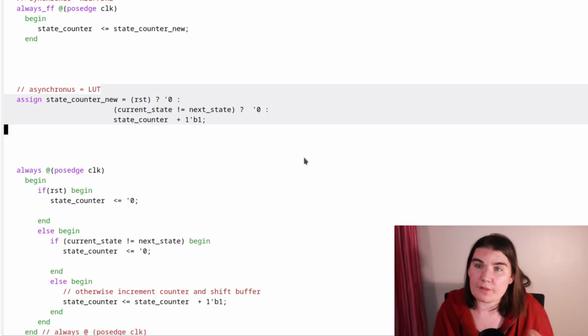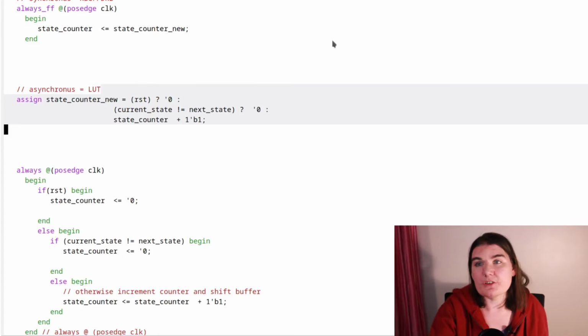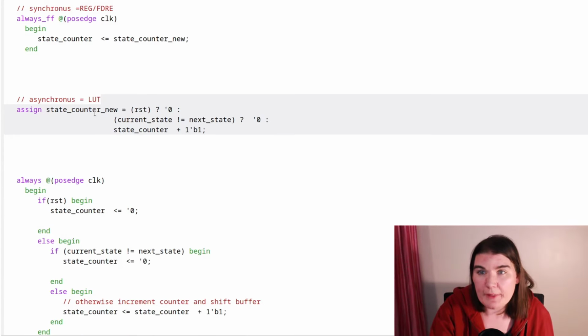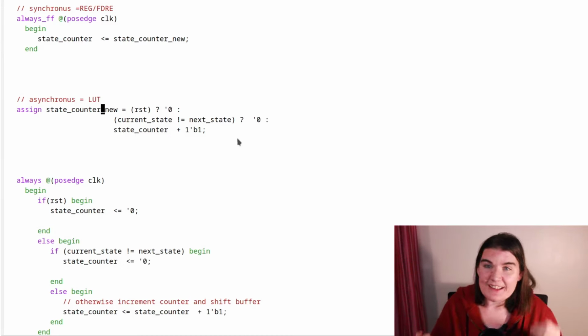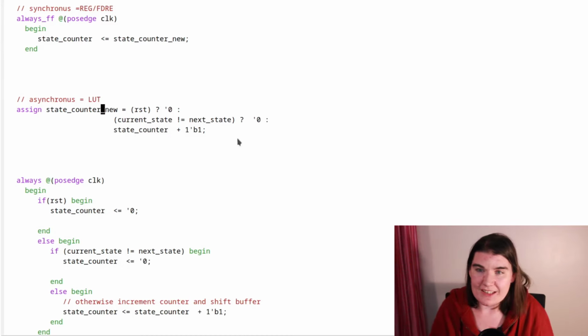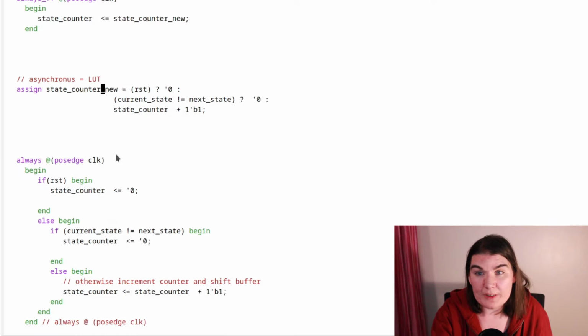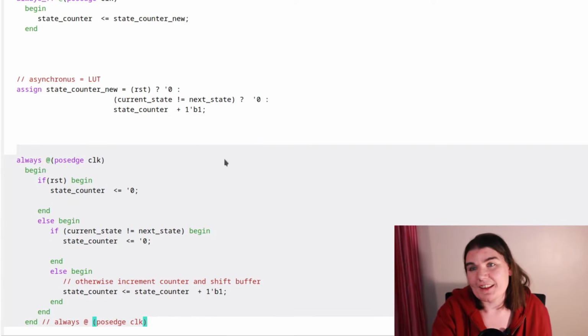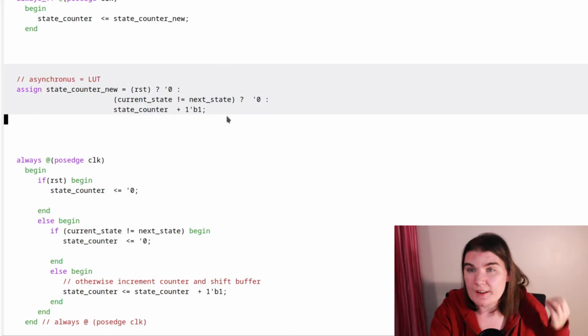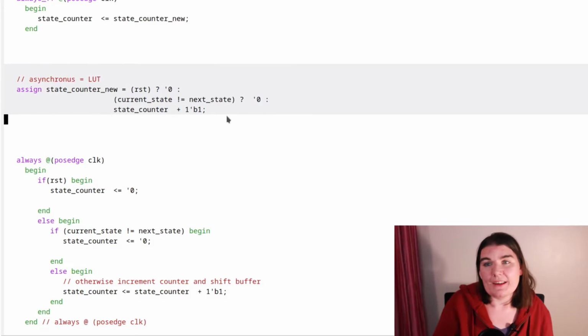These are the functions of the always block. If we drive a signal by itself, then we will infer a latch in asynchronous logic. Synchronous logic is logic that contains a clock, like this always block. Asynchronous logic is logic that doesn't contain a clock, like this mux.